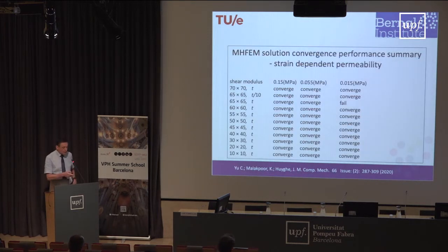So now we can go back to our simulation, look at what happens when we take down the stiffness to 15 kilopascal, and you see that most of our simulations nicely converge. And so this is what we want. We want an absolutely reliable finite element analysis which can be used routinely without each time getting responses like, oh, this calculation doesn't work.